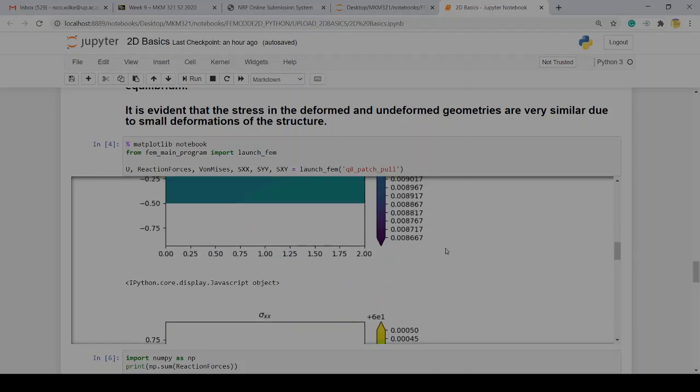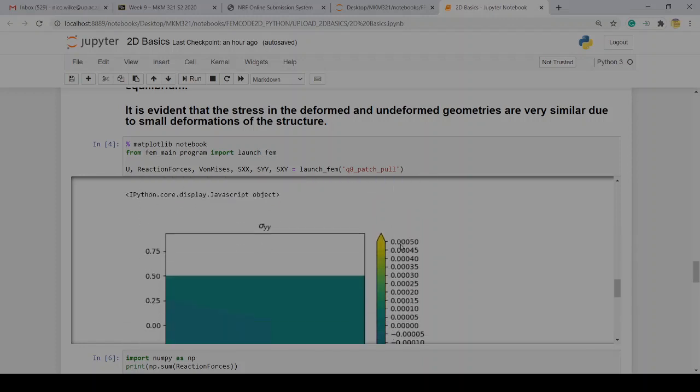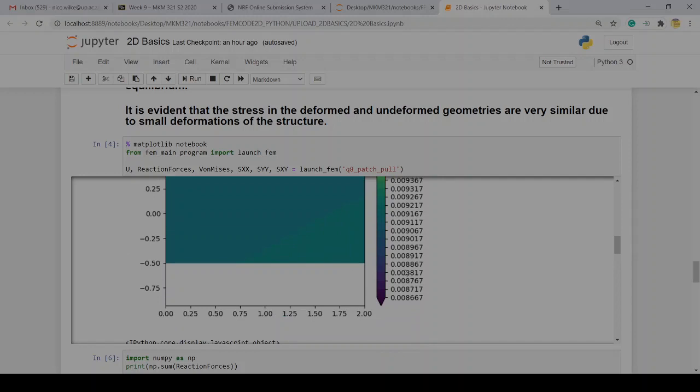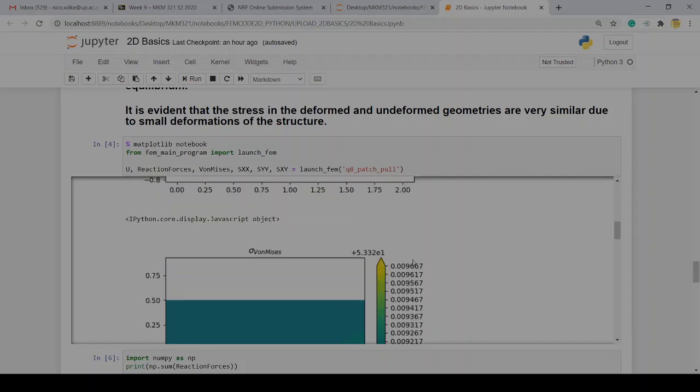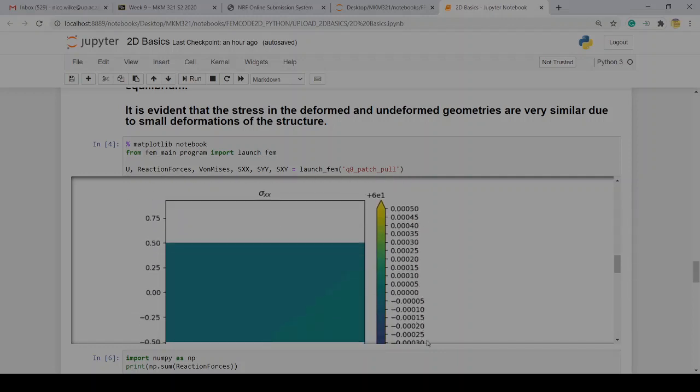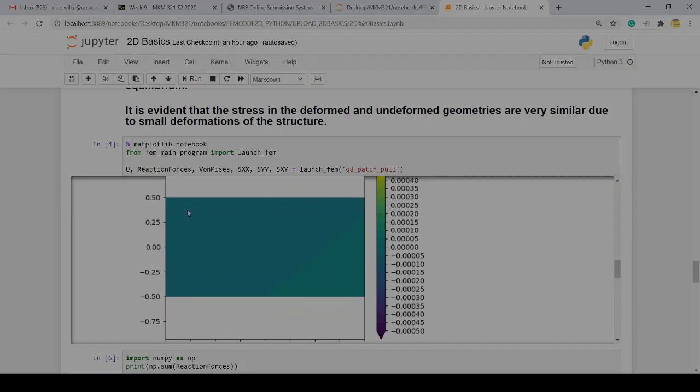You have to interpret these values and understand that we are working with values that have quite large units. We're working, for instance, with Young's modulus in terms of MPa, and those are the magnitudes of the numbers. In the context of those sizes of numbers, with finite precision, this is essentially evaluated to 0. So you can see 53.322 whatever plus this is essentially dust, as 0. The 60 plus this dust as 0, and this is nice and uniform across this.